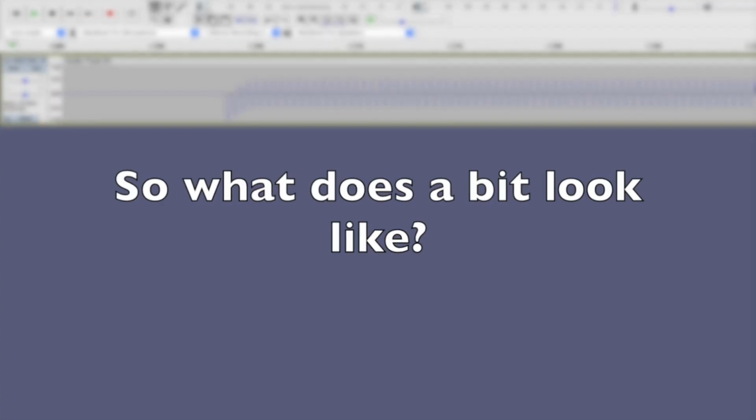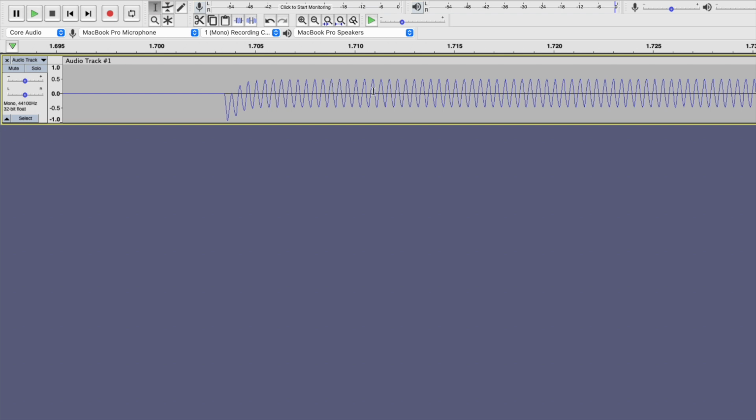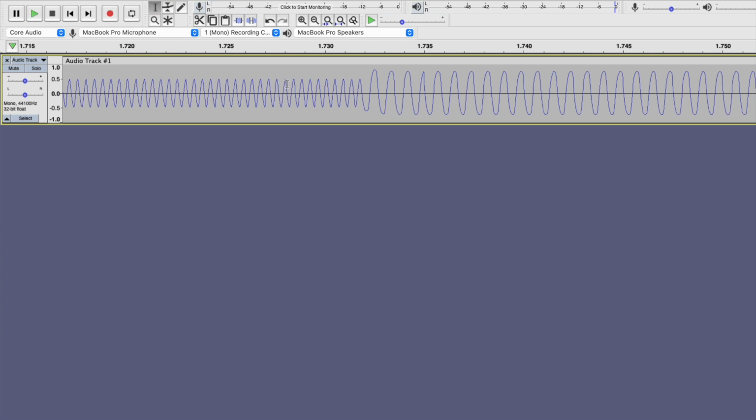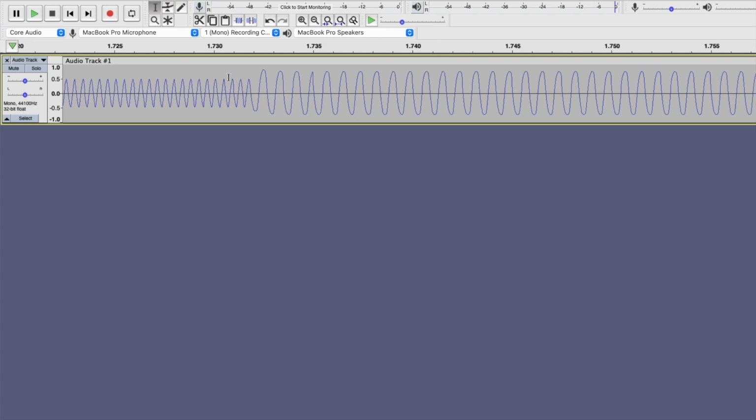First, it needs 1 or 2 cycles to stabilize in the beginning, and then it just keeps outputting leader marks or 1s until it reaches the first 0. Technically, the waveform is inverted here, as this is a cosine wave instead of a sine, but it doesn't really matter because all we care about is the distance between zero crossings.